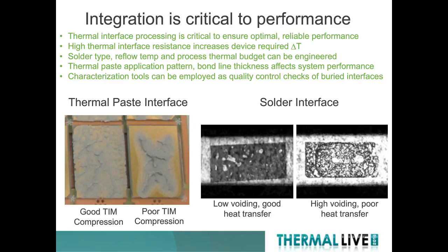So the dispense pattern of whatever interface material you're using, the amount of compression applied to achieve desirable bond line thicknesses, and even things like thermal budget when you're working with a solder, those can be engineered to make sure that you are not running into thermal budget issues with the next higher assembly or with the component itself.